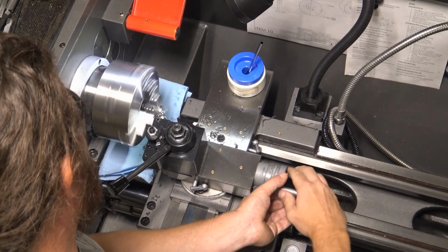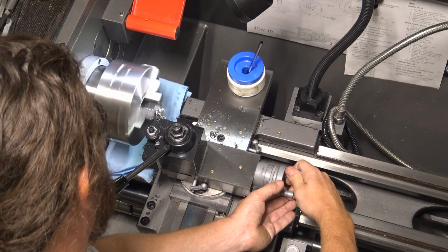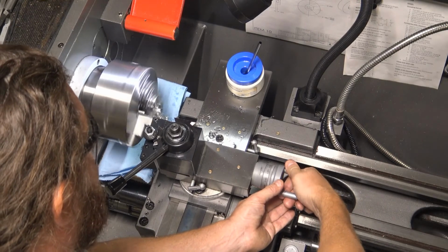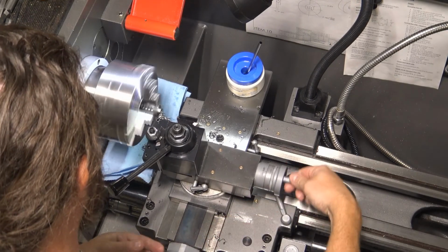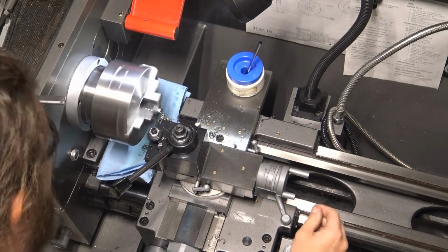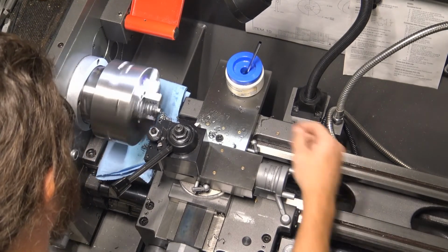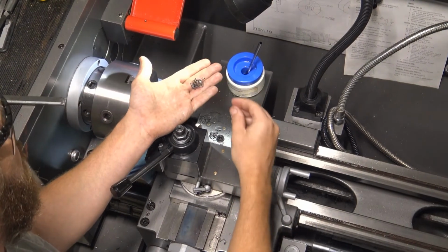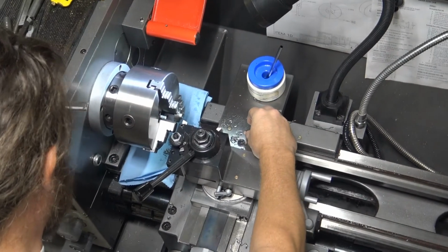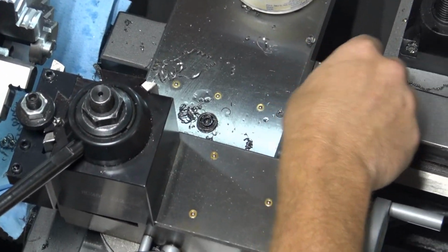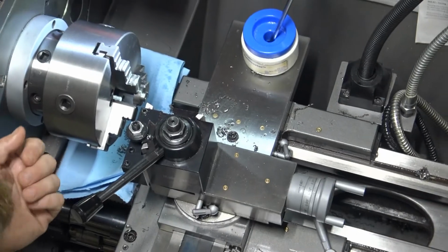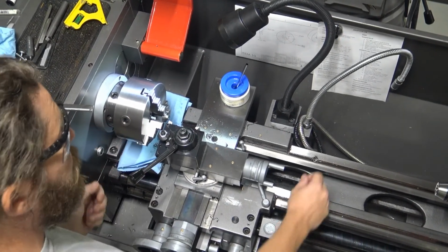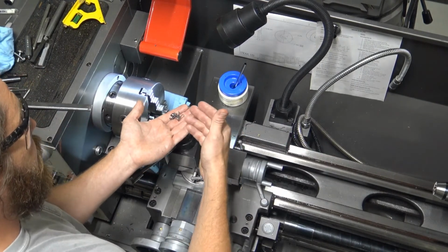You can see those chips curling. That's a pretty good chip and how they should look when they come off the tool. All right, there's 180. Out in front of the part. So these are good chips. This is what you're looking for when you're cutting. If it's all just small little crumbles, like little crumbs, then you're probably going too slow. And when you go too slow, you build up too much heat in your tool. We want to keep the heat in the chip as we're cutting.